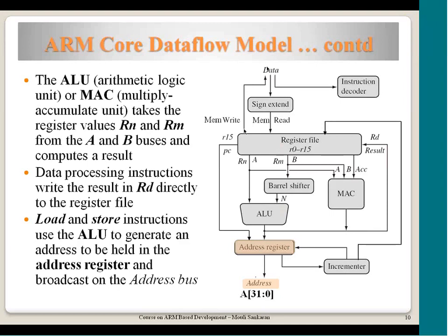So during the data read or write, these circuitry don't come into the picture, and the data to be written goes out from the register file into the data bus through this part. Okay, this is the explanation for load and store instruction, how it gets executed here.